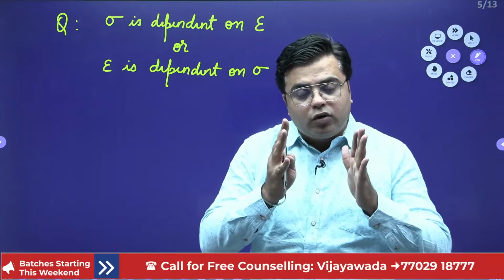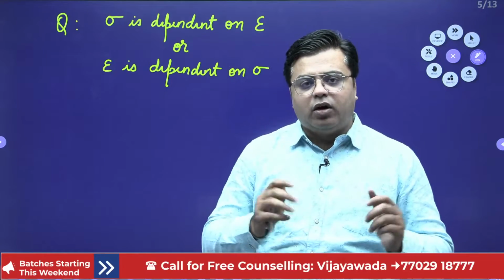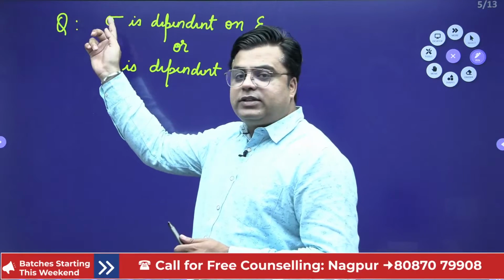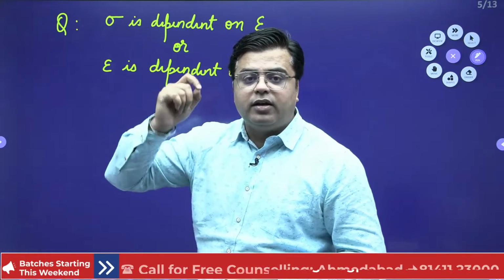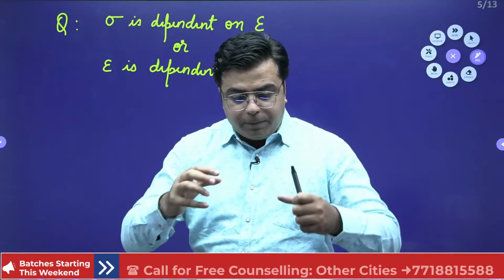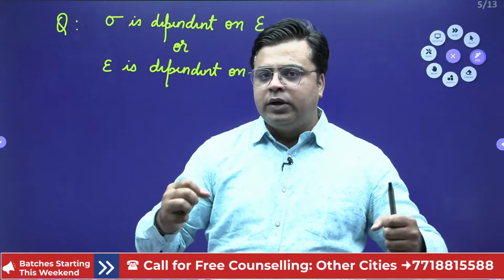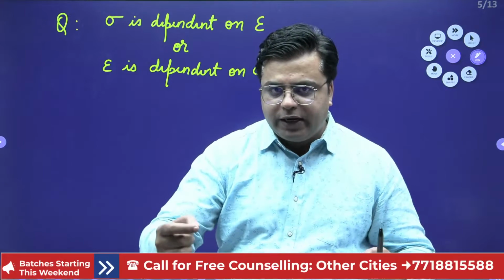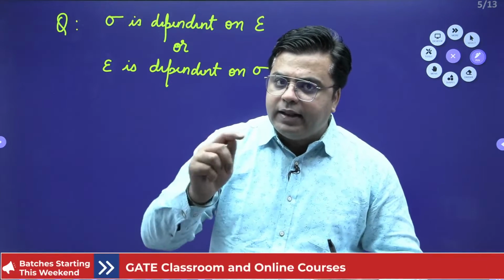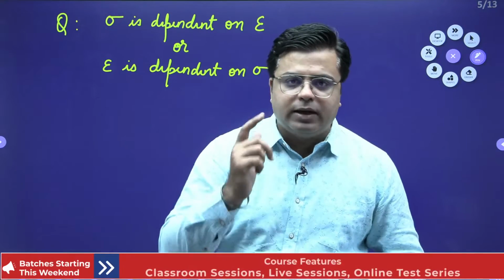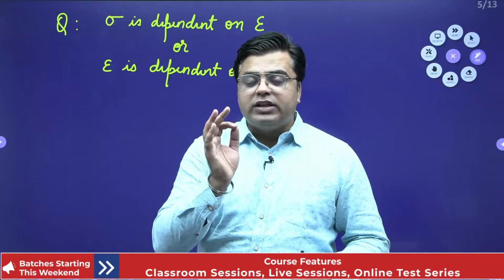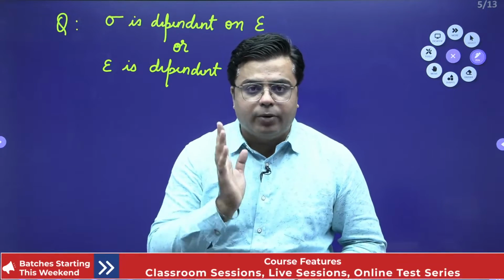In order to resist this deformation, internal resisting forces are produced. So first, the body undergoes deformation. Due to this deformation, strain will come, and in order to resist this strain, internal resisting force will develop in the body. And due to this internal resisting force, your stress will develop in the body.